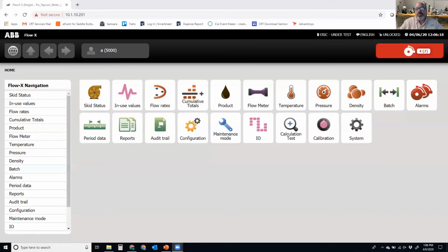The FlowX, we don't do that. What we're looking at is what is the process variable coming into us. We want you to calibrate the transmitter, but we're not recording that within the flow computer. We have made some changes to our gas application, and we're going to be implementing them in the liquids application. But what we're going to be verifying here is we're assuming that you've already calibrated the instrument. Now we're going to be calibrating the process input, the 4 to 20 milliamp signal or the 1 to 5 volt signal.